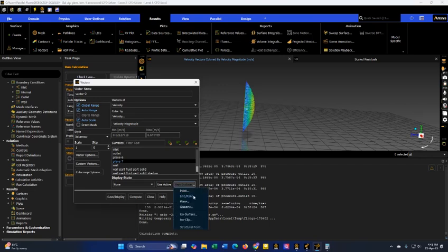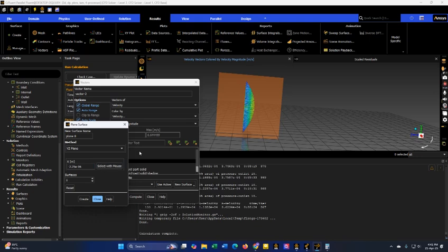And if you want another surface, let's say another plane, the xy plane again, and give it a distance so that the flow will be some distance from this. So give a distance of, let's say, 0. Our length is 0.75, so make sure that the value is inside that range.